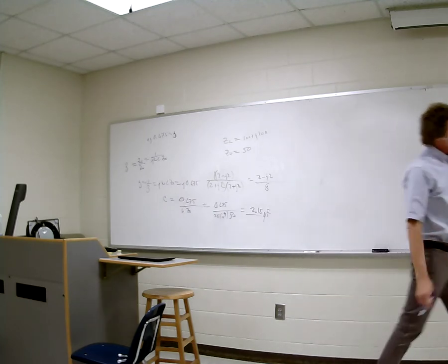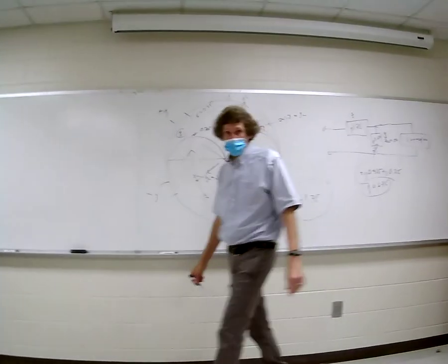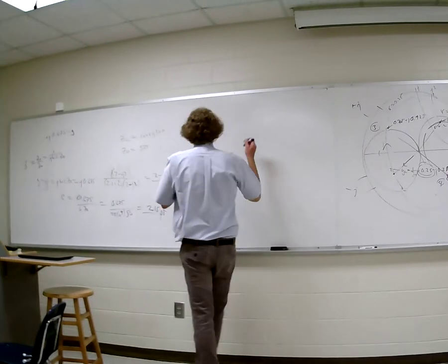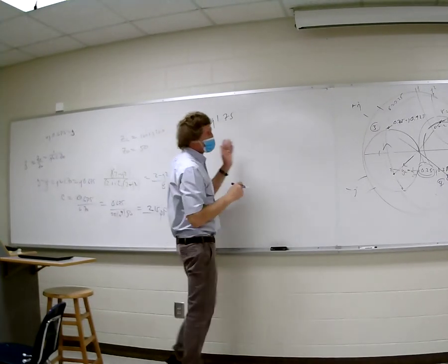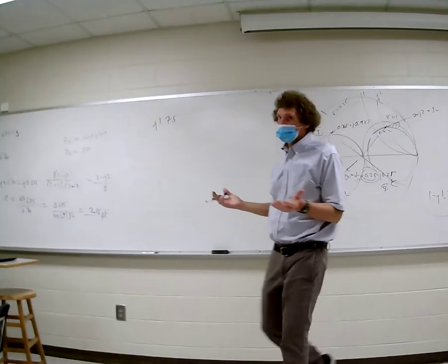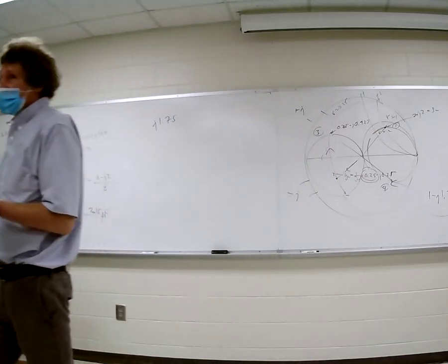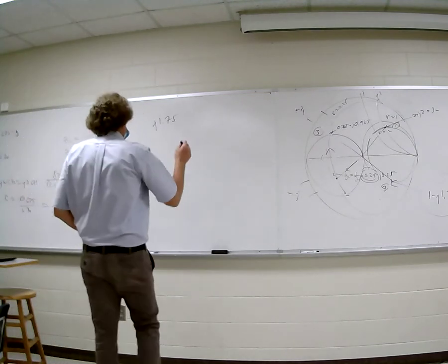We've got the normalized value of impedance, right? 1.75, right? So we have j1.75 over here. That's normalized impedance. What has an impedance of plus j something? An inductor, right? An inductor has an impedance of j omega L. Do you all agree with this? All right. So we set it equal to j omega L.